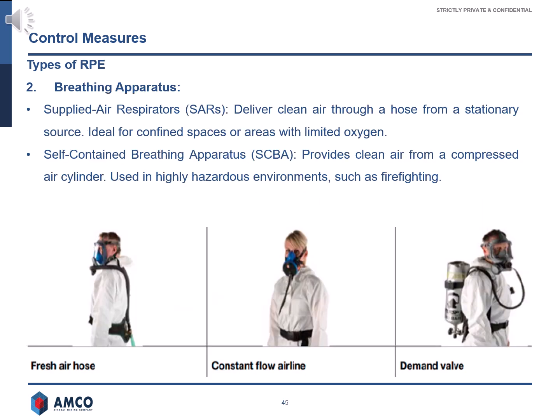Breathing apparatus. Supplied air respirators, SARs, deliver clean air through a hose from a stationary source. Ideal for confined spaces or areas with limited oxygen. Self-contained breathing apparatus, SCBA, provides clean air from a compressed air cylinder. Used in highly hazardous environments, such as firefighting.